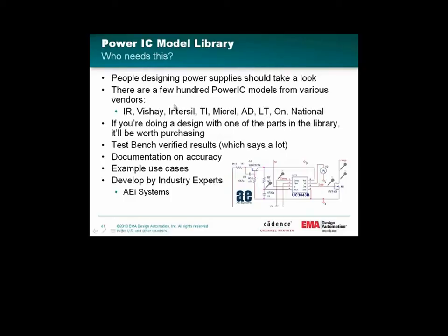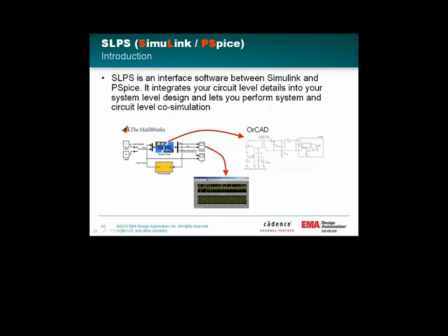First, before I talk about Advanced Analysis, let's hop back one slide to SLPS. SLPS is a tool that integrates your PSpice with MATLAB. If you're using Simulink from MathWorks and you would like to put some circuit intelligence into that Simulink flow, you can do that with SLPS. SL stands for Simulink, PS for PSpice. It allows Simulink to be the master of the simulation. It runs its simulation, but as it's running along, it talks off to PSpice, so you can put real PSpice circuitry right into your Simulink flow and do co-simulation with the two.